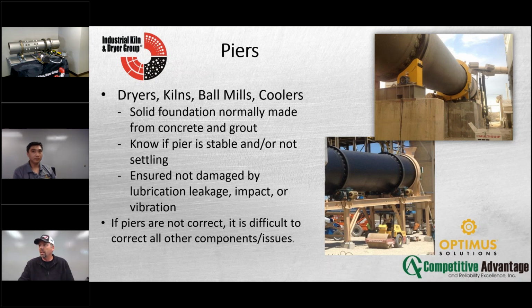So right, it's a design. Well, I would say when we get a lot of vibration types of questions or concerns, one of the things I ask is, is it loose? And if you can't define it as loose, then we have a technology that we can look at the vibrations to see the looseness. Which is a pretty cool tool. If you guys have questions, you can ask me on that.